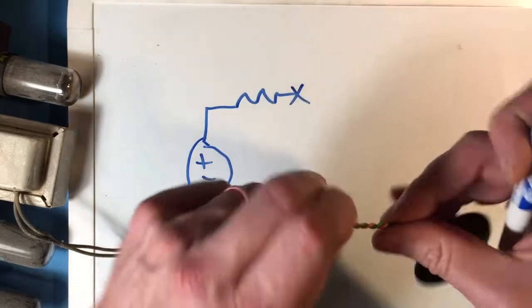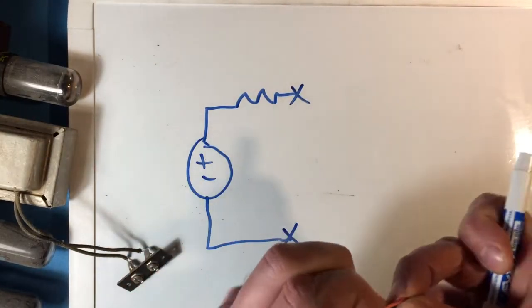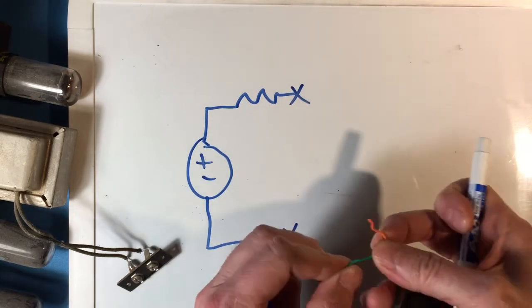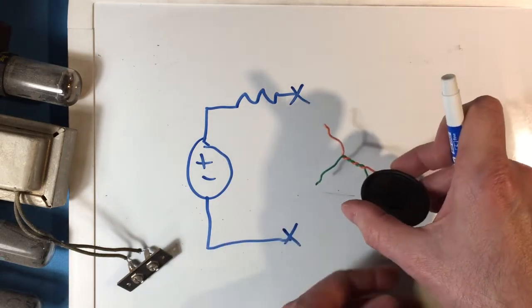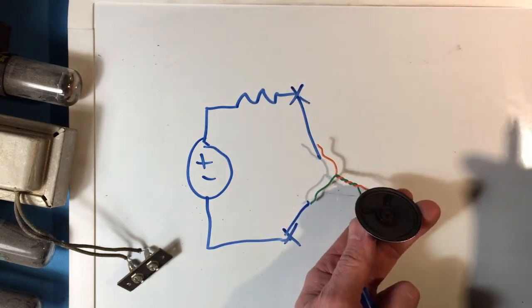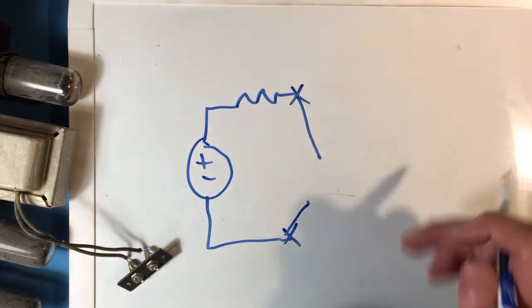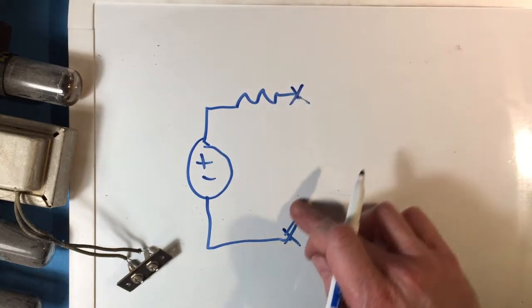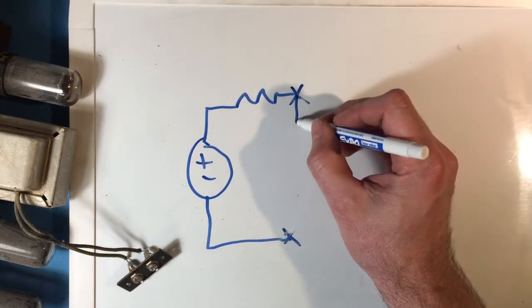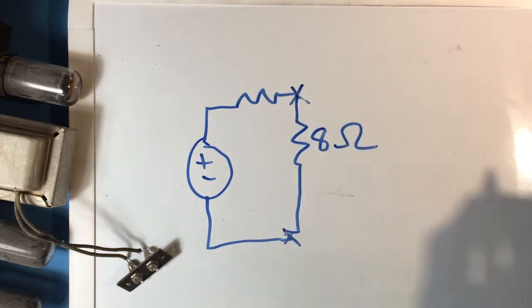And there are 2 wires on our loudspeaker, and literally we want to know, how do these 2 devices interact when we connect the wires up, right? Like if I wired those 2 things in right there, is this amplifier going to work? Is it delivering the maximum power to the speaker or not? So because the speaker looks like an 8 ohm resistor according to the back, we could put an 8 ohm resistor in here.